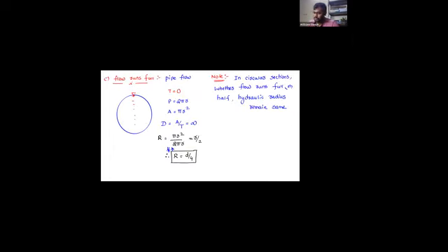And you see one more point over here. So what is a Froude number? In the case of open channel flow, you are going to use the Froude number or not? So that Froude number, Fr, is nothing but V by root gL. Yes or no? And now, my dear, V is a function of R, whereas L is going to be hydraulic depth.